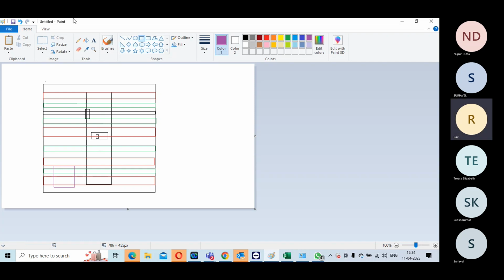You understood? But when you have cells spread in a particular region, you can add, like in the AMD flow, a breaker cell on either side, everything M1 connected, but here you will have always on power supply. It can move. Always on connection, and then this breaker cell. Even if you have one cell which is always on, either side of it you need to have a breaker cell. You understood? Yes, sir. Yes.